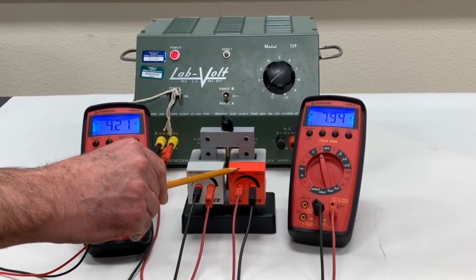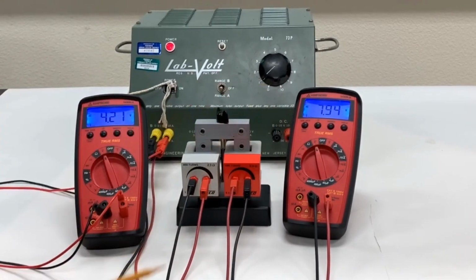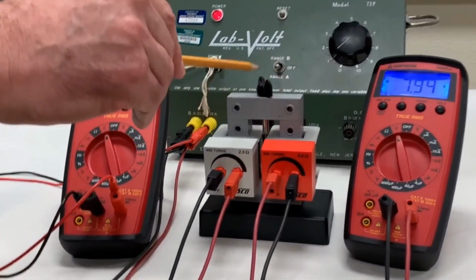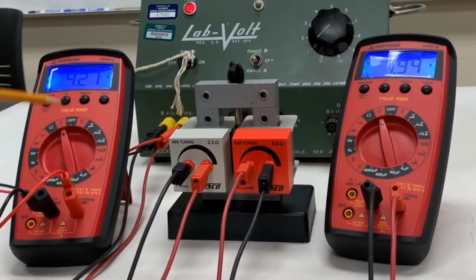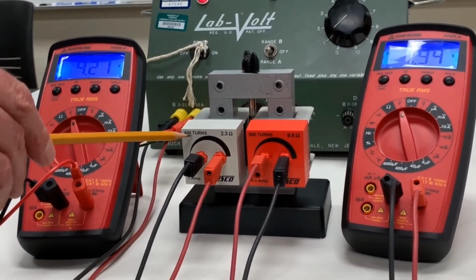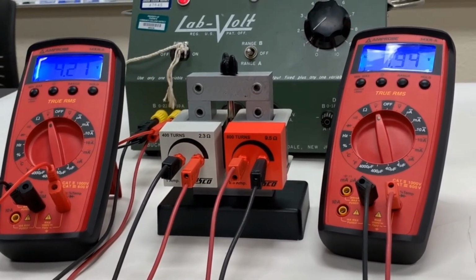It's not a powered coil, but it is connected to this voltmeter over here. And you'll notice also that these two coils have their fluxes linked via this ferromagnetic core, which penetrates the interior of both coils. The primary coil on the left has 400 turns. The secondary coil on the right has 800 turns, twice as many turns.